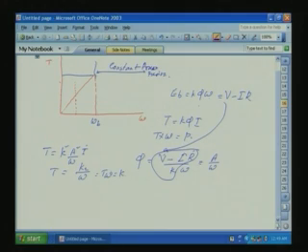Now, if you see here, torque will be inversely proportional to phi. When we slowly change phi in proportion to omega, torque will be inversely proportional to omega. So here the speed torque characteristic will go like this. Up to how much we can go also depends on the bearing and the mechanical design. Usually 1.5 times, 2 times above base speed we can go.